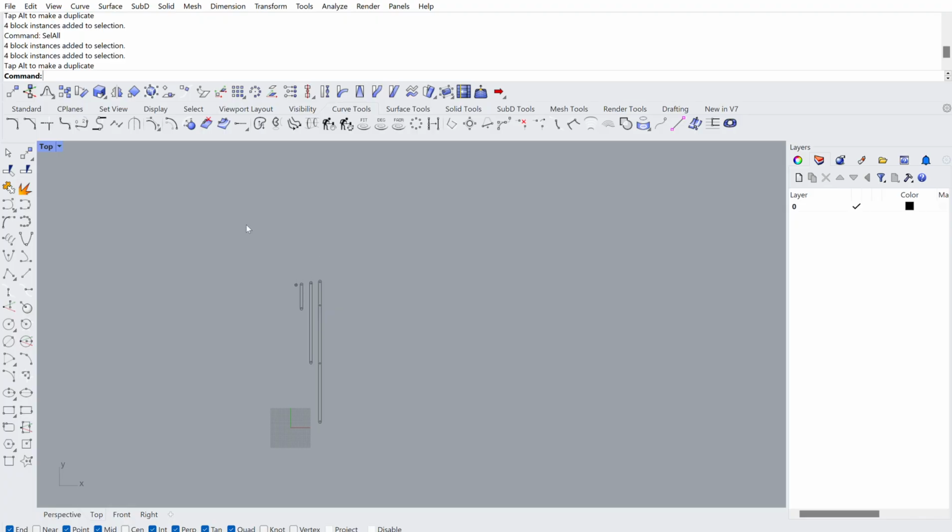And then as far as selection tools, as with many vector programs, if you select from left to right, it selects anything that's fully in the selection window. So this was fully in, this was fully in, but these ones weren't. Oh yeah, actually these are block instances, so they're grouped. And if you select from right to left, it selects anything that touches that selection window.